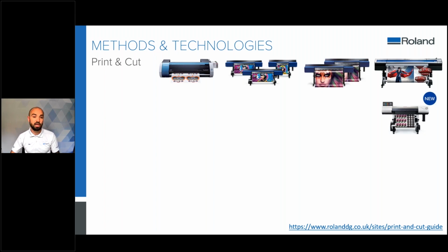So you'll put in normally a white vinyl, but they can print onto some colored vinyls, reflectives, silvers, or chromes, so there are a whole range of other vinyls that you can print onto. Again, we'll come to those a little bit later. But normally you would print onto those films, and then there would be a contour cut that would go around the outside. So the benefit being that you don't just have single color graphics like you would with a cut vinyl, and you can create just about any design because you can print photographs, vectors, a mixture of the two, just about anything, and you can cut out certain elements to put those onto different surfaces.